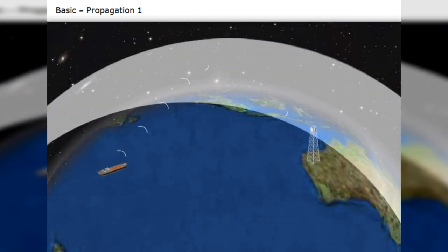Propagation. Radio waves travel from a transmitter to a receiver in 3 ways. Ground wave. The ground wave travels near the ground for short distances, typically 80 kilometers over land and 300 kilometers over the sea. This, however, depends on a number of factors, such as operating frequency, transmitted power, type of antenna, and terrain. Typically HF communications equipment.